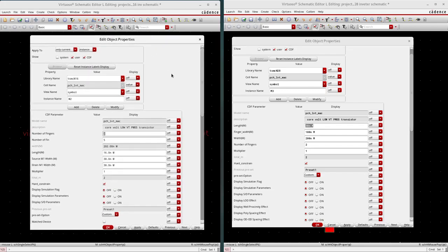This is our 16 nanometer design. In the 16 nanometer design, only the LVT device has the lowest gate length of 16 nanometer. If you are going for a high VT device, SVT device, or some other intermediate voltage device, then the gate length won't be 16 nanometer; it will vary. It will always be higher than the lowest. So only LVT devices use the lowest gate length of 16 nanometer.